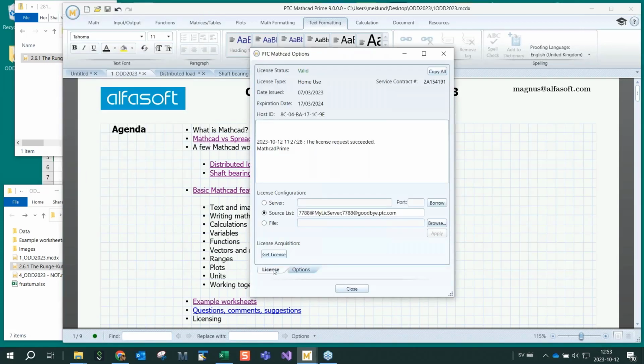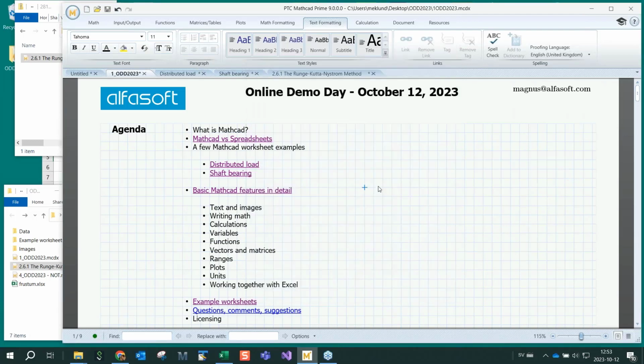If you're using floating licenses and you're allowed to by the administrator, you can borrow that license and go offline, on a trip or something. If you need to go on site and just can't access your network, that's a good function. I borrowed this license for a week. And if I get back earlier, I can go back and return that license. And if you forget? Then it will take a week until the license gets back to the pool.